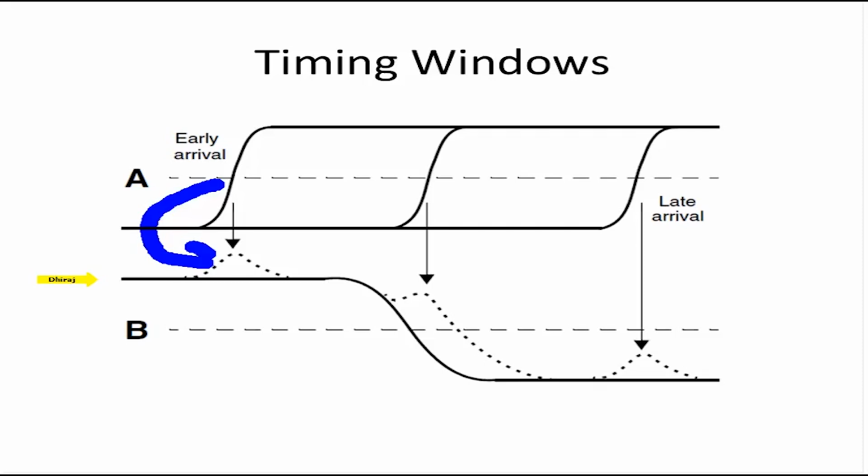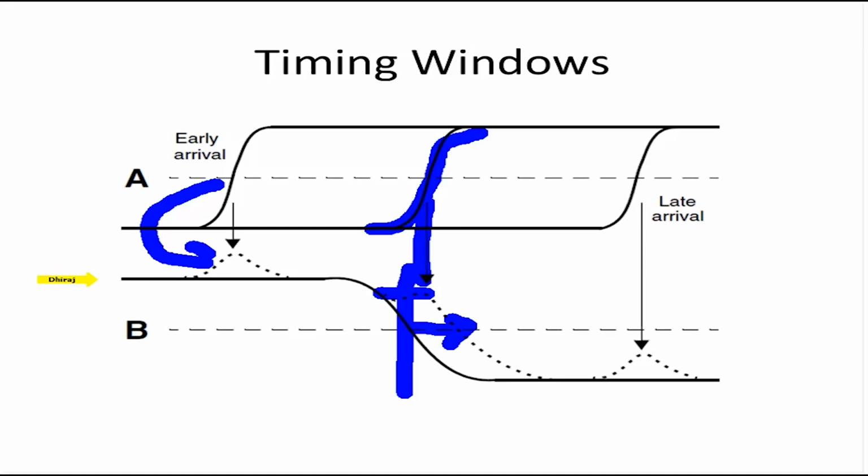But now the victim is switching, and any switching of the aggressor here, when the victim is switching, will now cause delay. Since it's switching in the opposite direction, it will cause it to delay further. Now please remember, the delay is usually from the 50% threshold, but now the 50% threshold moves to the right, so there is more delay. Again, if the aggressor switches late, it will only cause noise.